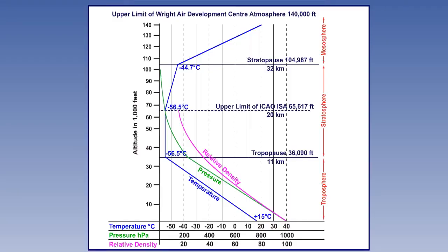On the basis of these assumptions, the pressure which corresponds to any given altitude in the ISA can be calculated, and under laboratory conditions, any altimeter readout can be checked against the ISA calculated figures. Any discrepancies within accepted limits can be listed as instrument error over the operating range of the altimeter, and can be recorded on a correction table for the altimeter.